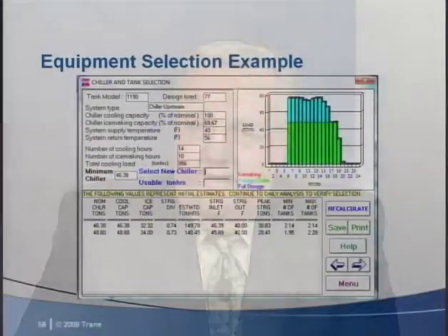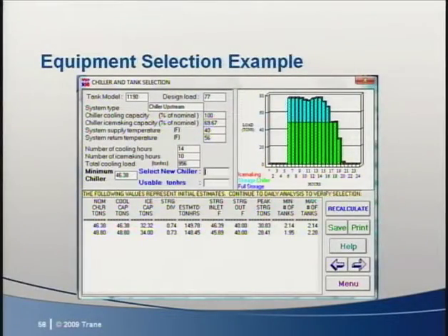Can you show us this in the IcePick program? Sure. First, let's look at what happens if we input an actual chiller selection. Then we'll follow that up with increasing the chiller to the next cataloged size. The closest chiller to the minimum capacity required is a nominal 52-ton machine. The chiller catalog reveals that it provides 48 tons at 95-degree ambient during the day and generates about 34 tons of ice each hour at night in 80-degree ambient temperatures.